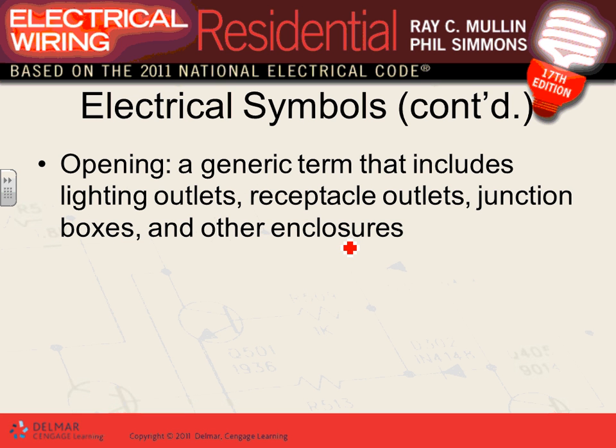Openings. There's a term called opening, guys. An opening could be a place where you have a lighting outlet, a receptacle outlet, a junction box, a switch. I grew up in Jerusalem. When I was doing electrical work there, and it's actually here too in Minnesota, when we estimate electrical power, some people estimate based on how many openings you have. Every opening is $50 or $40. An opening is a location for a receptacle, a switch, a lighting fixture. Count all these and multiply them by $40, and you get yourself an estimate for that particular project.